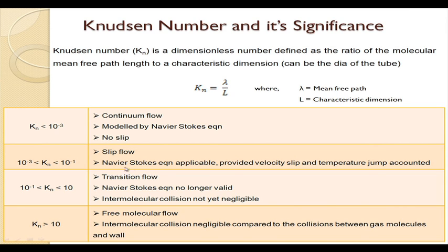The Navier-Stokes equation is still applicable, but we have to incorporate velocity slip and temperature jump. If we go to a still higher Knudsen number, the Navier-Stokes equation is no longer applicable, because wall fluid particle interaction becomes much more important than intermolecular collisions, and for still higher Knudsen number it becomes a free molecular flow and the single phase equations are no longer applicable.